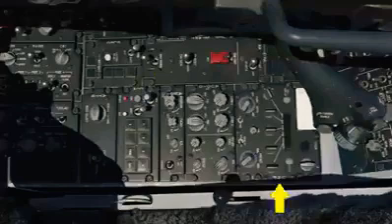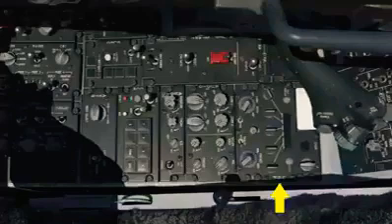While most of your radio use will be through the Integrated Control Panel or ICP, and the data entry display or DED on the instrument panel, a backup UHF radio head is also available and must be used before engine start, as it's the sole radio that functions only on battery power. For those familiar with our 810C, this is the exact same UHF radio.